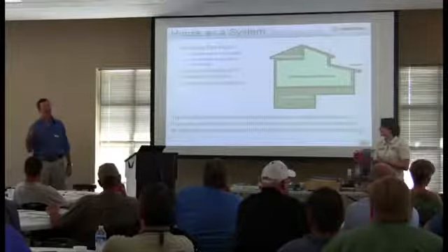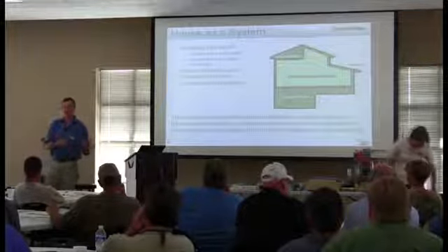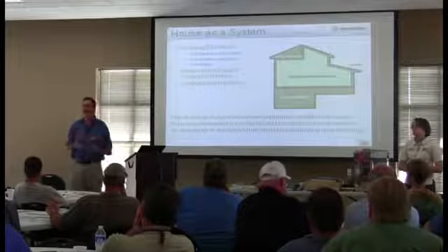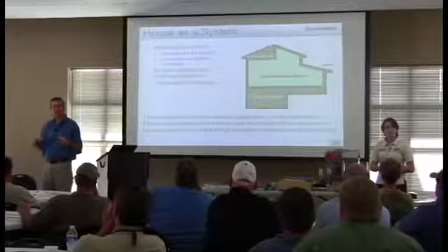So it's something to think about, that as we start building tighter homes for energy efficiency, we might want to start thinking also about bringing in outside air, not because the house needs to breathe, but because the people in the house need to breathe. Does that make sense?